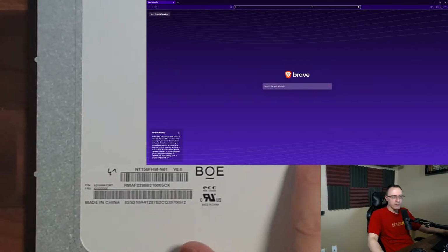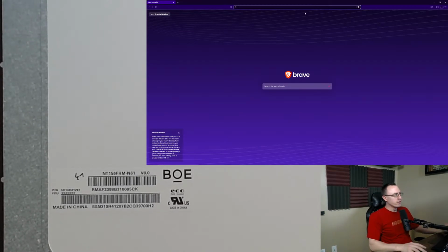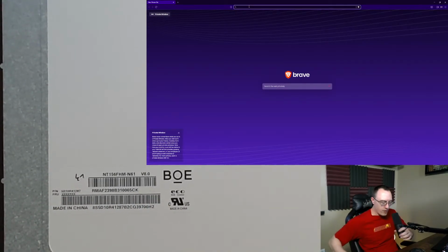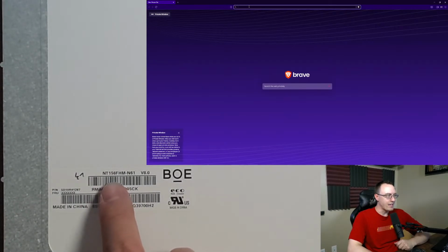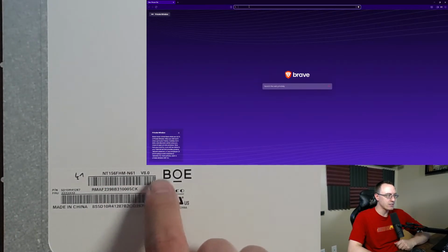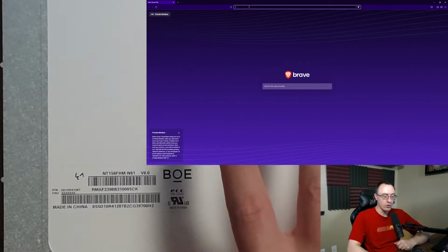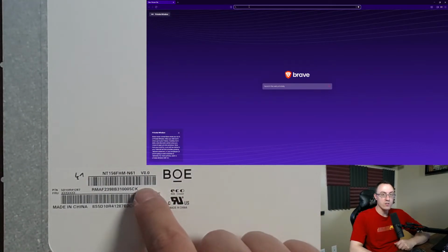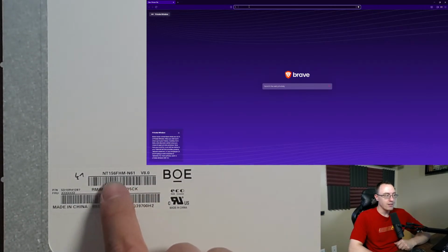So what we have here is sourcing the LCD from this Acer laptop. Fix my posture, make sure that's all good. There's a lot of different numbers on the bottom here for this screen. And you might be looking at me like, okay, what the heck are all these numbers? So at the top here is the universal number, NT156FHM-N6V8.0. That's like the manufacturer's number for this screen. That's the generic for anything on this screen, because this screen can go into hundreds of different types of laptops. So when you're looking for it, you mainly want to match that number.